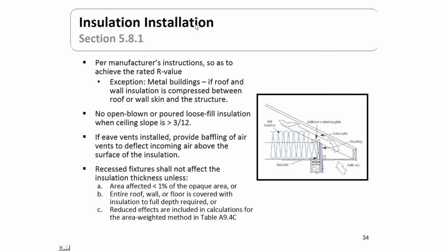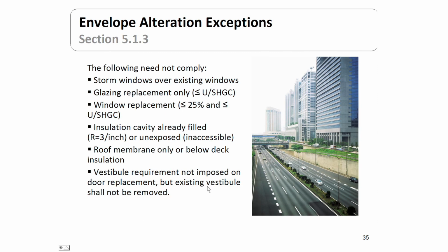This is a requirement on how the insulation's to be installed. To sum up quickly, the picture here shows insulation in the attic being pushed up near the wall edge. The main requirement is simply to make sure that that insulation does not block off this natural ventilation that comes in the soffit vent and goes up the roof and out the ridge vent. Blocking has to be put in there to prevent that insulation from being pushed clear to the edge.